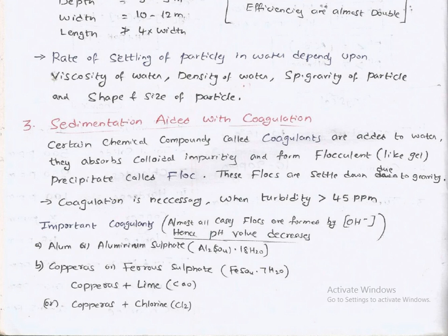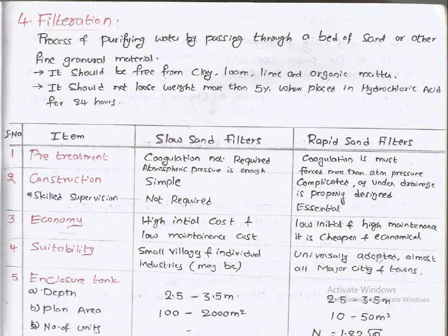Filtration: the process of purifying water by passing it through a bed of sand or other fine granular material. The sand should be free from clay, loam, lime, and organic matter. It should not lose weight more than 5% when placed in hydrochloric acid for 24 hours.